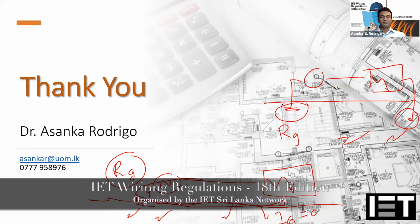Okay, right. So the next question is, what is the average leakage current of LED lights? And is there any sum of leakage current, percentage leakage current, that can be connected to any RCD rated residual current? Two questions. What is the average leakage current of LED lights? Actually, when you look at LEDs, the leakage currents are coming from the EMC filter. The new LEDs have an EMC filter, and this EMC filter will create a certain type of leakage current, but those are high frequency. What we have to do is give a path for this high frequency current to go to the source. Because when you aggregate those high frequency components, they will be detected by an RCD as total leakage current.